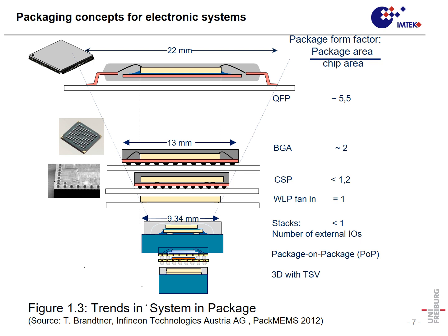These devices could be made smaller and smaller, and if the device is only 20% larger by area than the chip, it is called a so-called chip scale package. In the end, people had more and more ingenious ideas, and so chips could be stacked inside the package.